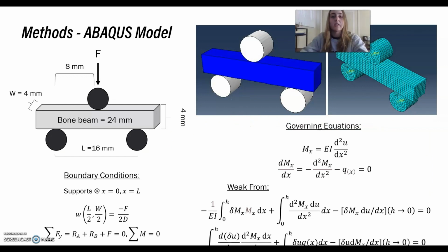So here in this slide, I'll combine looking at some of the boundary conditions and these equations that we're using, as well as how the Abaqus model was developed for this simulation. Once again, we have this fixture and this system, and this is just mocked up, the 3-point bend test. And in Abaqus, the mesh is a global size of 0.5.